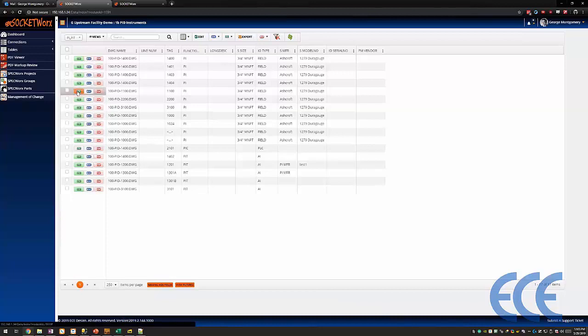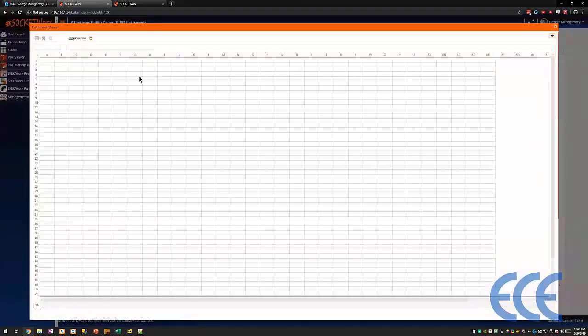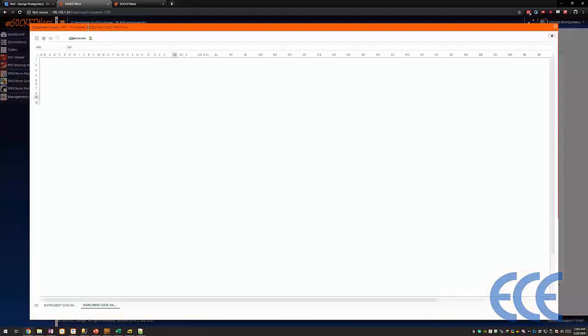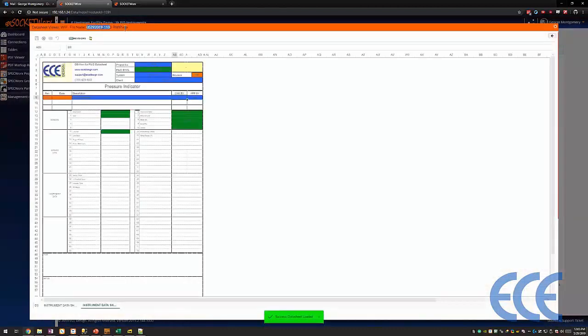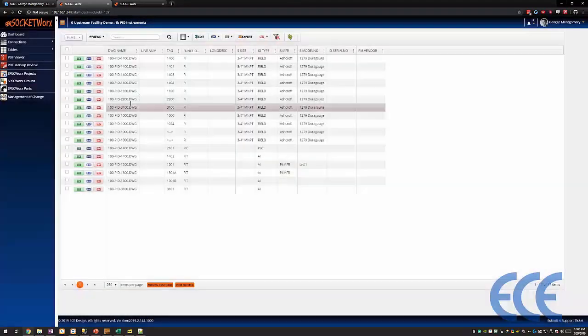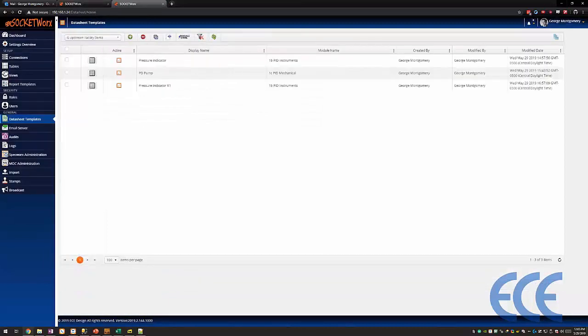First, I have to apply a naming convention to the datasheet itself. Because if I were to click on this now, oh, yeah, it already came in. Okay, so I do have a convention that's here. This is date dash tag dash the revision, and then just what revision it is, WIP 1, 2, 3, 4. I'm going to go ahead and show you, even though I've set that up, just where I apply that naming convention. So I'm going to go to tables,